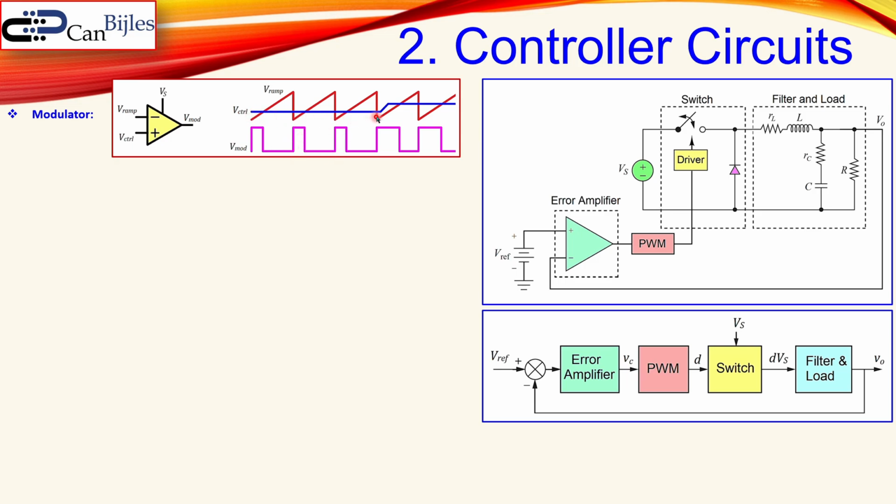So if the control signal goes up, so higher, we need more compensation because the output voltage, for example, goes to a lower value than we need it. Then the duty cycle increases. That means the switch is closed longer for a period, and that means we need to push more energy to the output. And you see that the duty cycle is then also increasing. Now the transfer function for the modulator can be calculated and determined from the average output voltage, which is this general formula we know. And that is again calculated using the on time from 0 to the on time itself.